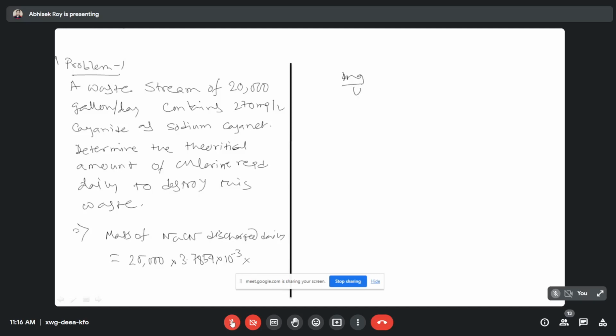Milligram per liter is as good as gram per meter cube. It will be same. So we will multiply by 270. So that much gram per day will be there. Okay. Now calculate how much it is coming. It will be 20,441 or 439, something like that, see. Yes, this much gram per day.